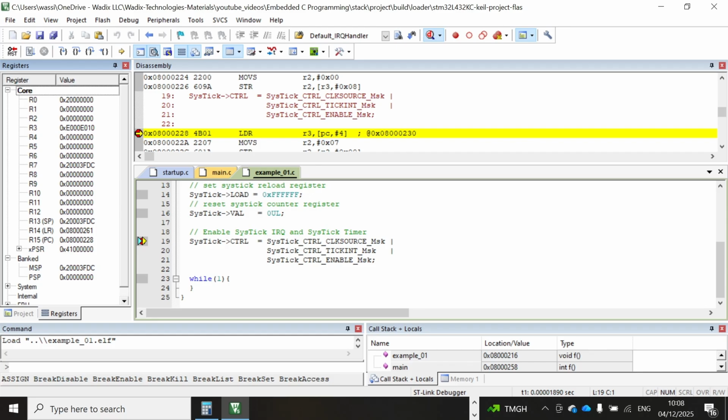Nevertheless, there is one important note: on Cortex-M, and to be more precise, in Cortex-M4 as well as M7, the processor will try to preserve 8 bytes alignment for the stack.